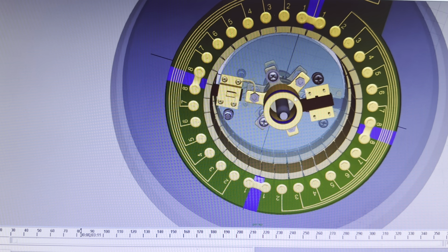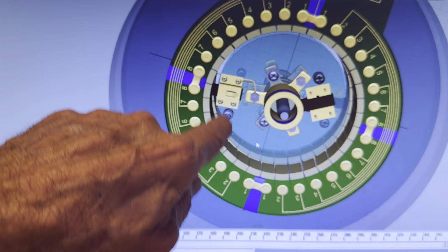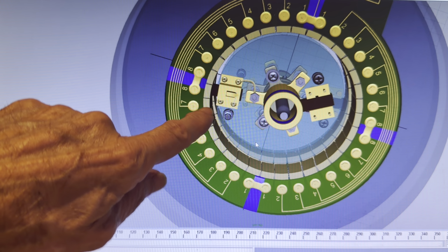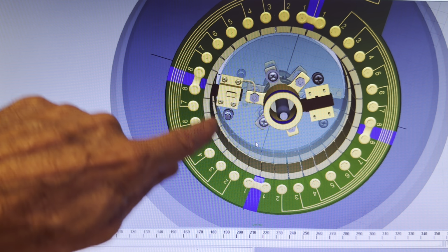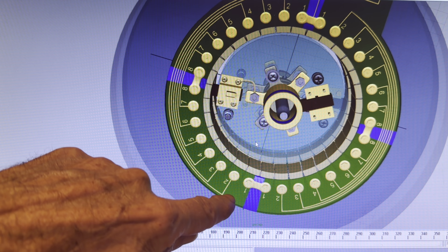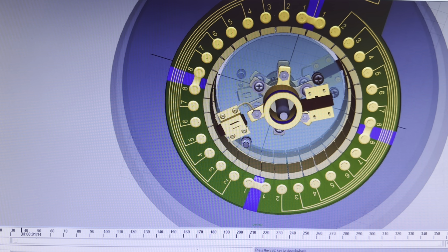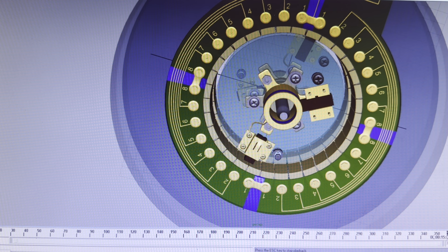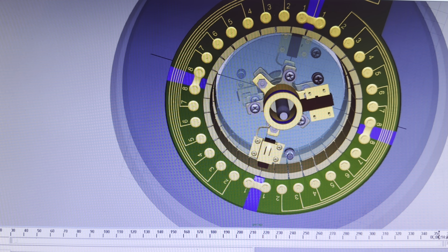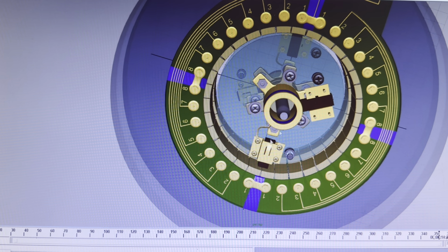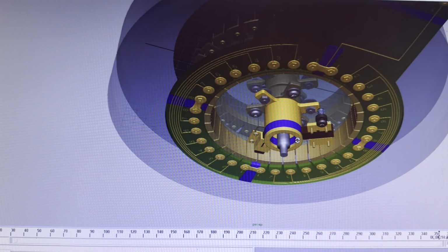situation. Remember, this negative brush goes counterclockwise, so here it is going to enter from 8 to 1 if I keep the rotation. Okay, and then I stop as soon as I get to 1 again. Now if we go to the other side,